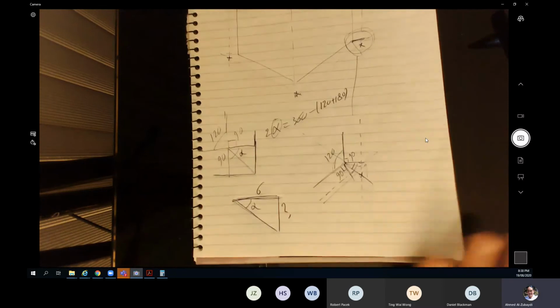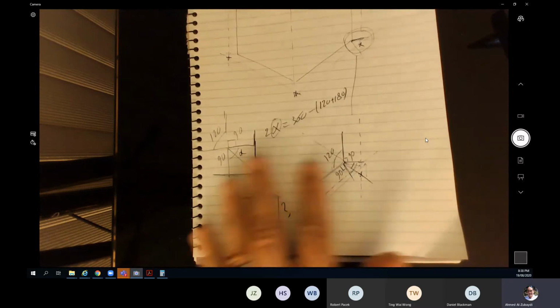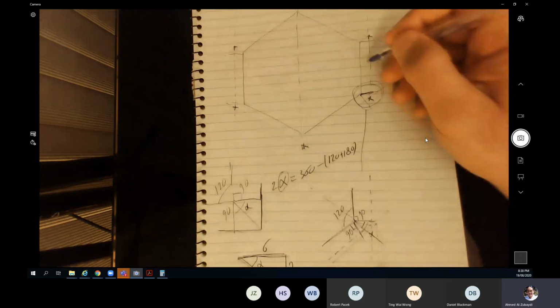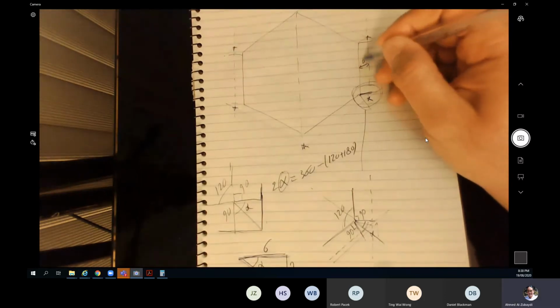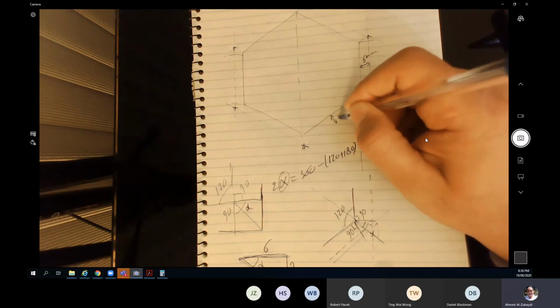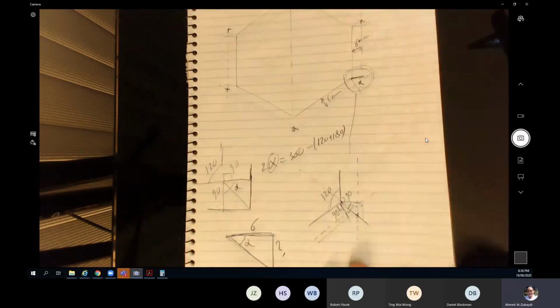Okay, so I'm going to keep this one, and you can do the same calculation. Just remember that the offset I had is 6 millimeter from all the sides, which is equal to the radius of the cutting tool I'm using.